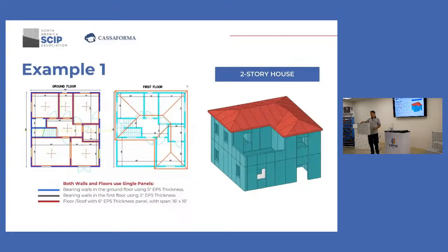Yeah, you can. The problem is that if the beam is very large, there are two issues. The first thing is that you have to ensure the connection, and this overlapping is okay if it goes up to the floor, but it's not okay for something that is working as a beam. Instead, if I place it horizontal, I don't have any joint.